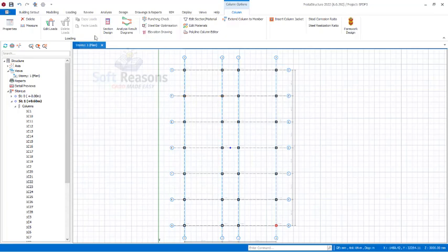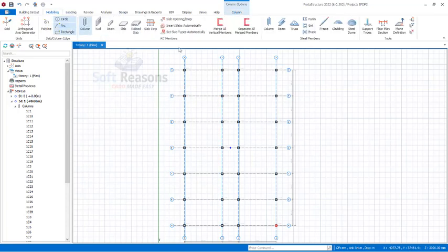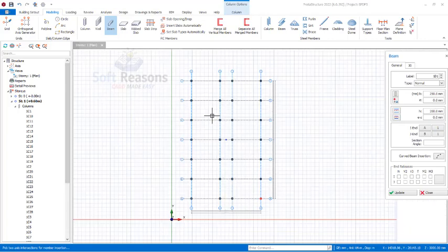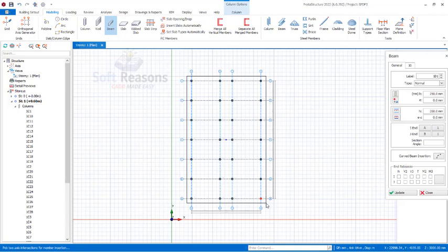The next thing is the beams. So we go to the modeling tab again, click on the beams member. So in the beams member dialog, just like this, we'll be having beams. The section width is going to be 250 right there, and then the depth of the beams is going to be 450, just like this, or we can just make it 350 right there. So we'll be placing this also automatically by holding shift over all the columns. Release our hands to have that placed really fast.